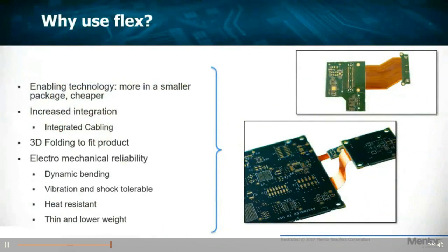Okay, so why use flex? If you're unfamiliar, why would you want to go into the endeavor of creating a flex design? It's a technology enabler. It allows you to pack more technology into a smaller form factor, and allows you to maintain a cheaper design by creating a smaller design. There's also increased integration between cabling and the actual printed circuit board design. You're able to incorporate some of that cabling that you might have needed in the past into the PCB design, including it in one project-based solution.